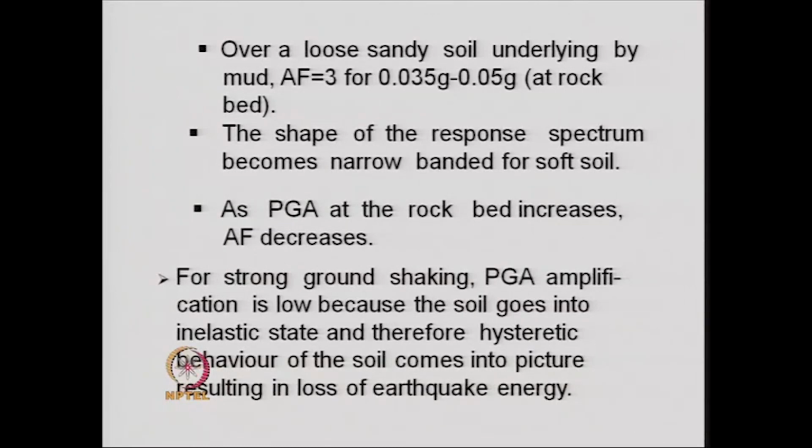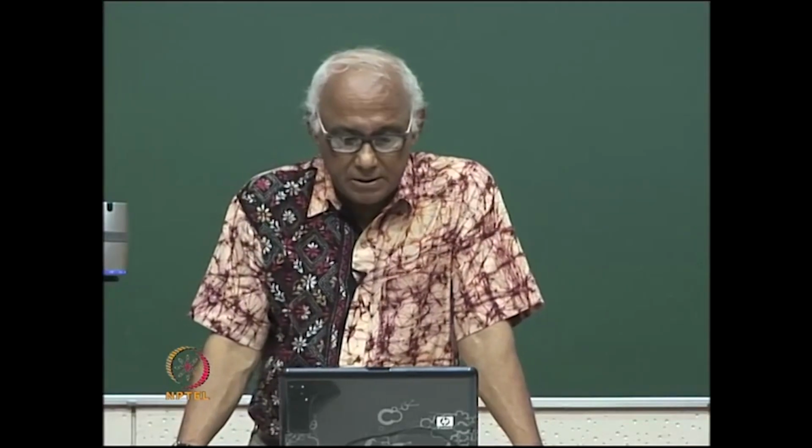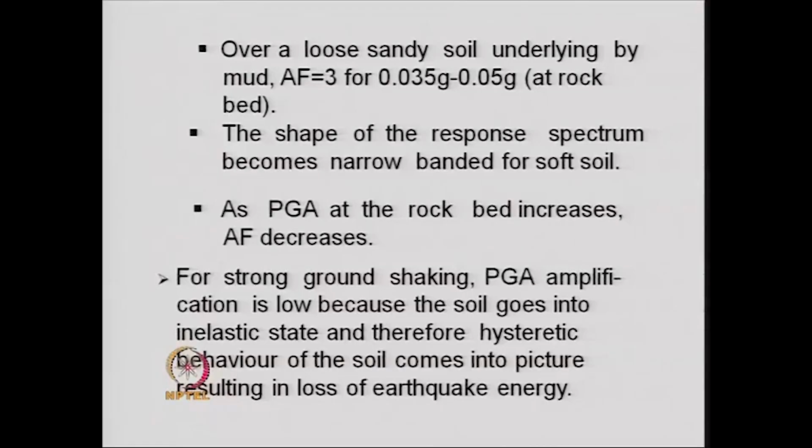This is due to the fact that the soil undergoes an inelastic hysteretic behavior under strong shaking at the rock bed, and therefore there is a tremendous amount of loss of energy while the seismic waves travel through the soil, resulting in a low value of the amplification factor.